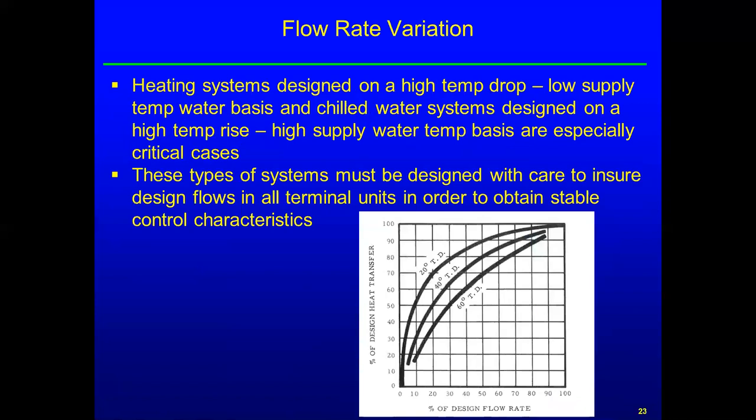Okay, so heating systems designed on a high temperature drop, low supply temperature flow basis, and chill water systems designed on a high temperature rise and high supply water temp basis are especially critical cases.